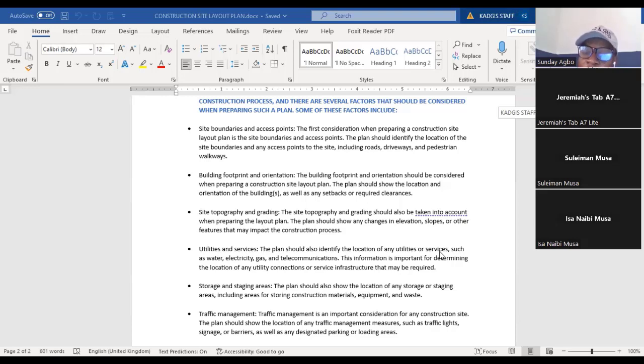So it comes to using GIS technology and then remote sensing or geotechnical survey to do what we call a GPR survey, ground penetrating radar survey, where we carry the machines that pass through the whole site to determine if there is any form of underground pipe. So all those things you need to put into consideration.